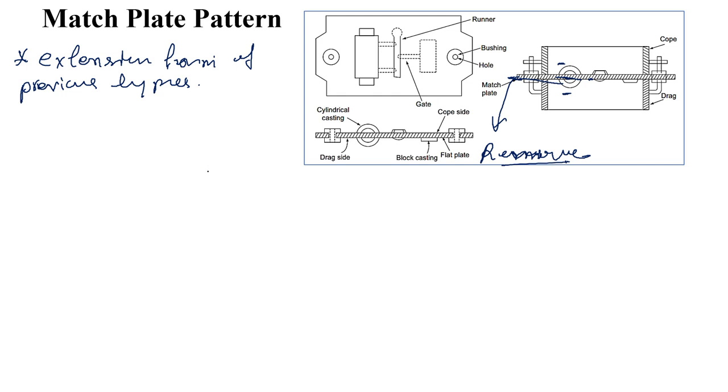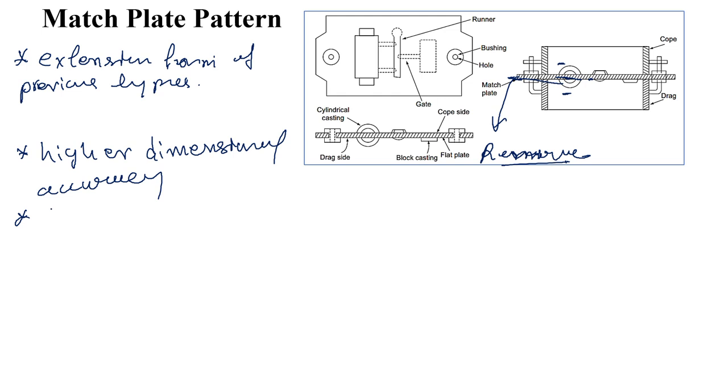These are generally used for castings which require higher dimensional accuracy, and second, for large production. And the gating system is already made and attached to the match plate.